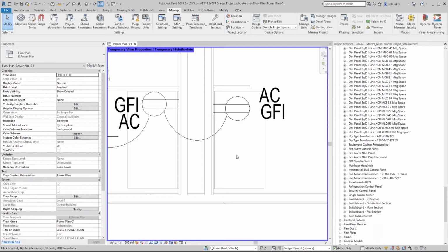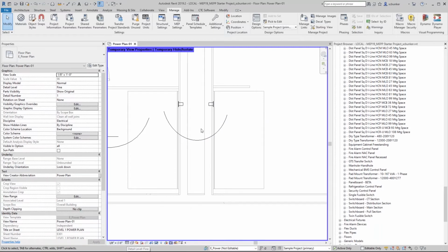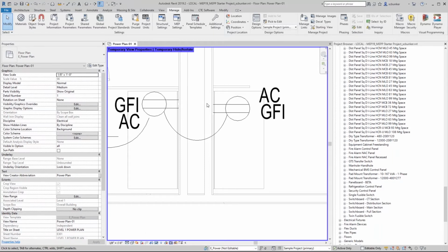A lot of content that you may have worked with in Revit, if you've used Revit before, uses view orientation to control that visibility. So if you know how families are made, you can hide geometry based on the particular direction that you're looking at it. The problem with doing that is you can't see the geometry in a plan view if you ever want to, and there could be situations where you want to. So instead of doing that, we've opted to control visibility of both the symbol and the geometry based on detail level. So if you're set to fine detail, you're going to see the actual device. And if you're set to either medium or coarse detail, you will not see the device, but will rather see the symbol.